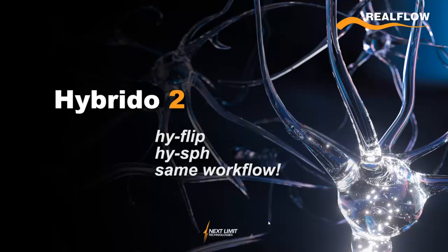The main one is that we are adopting a FLIP solver and we call it HyFLIP, and this is very important because all the bounciness that we got in the previous versions of the hybrid solvers disappears with the implementation of this FLIP solver, and it also means that the simulations are going to be running way faster and will allow way more particles. The reason for them running faster is because with the FLIP implementation